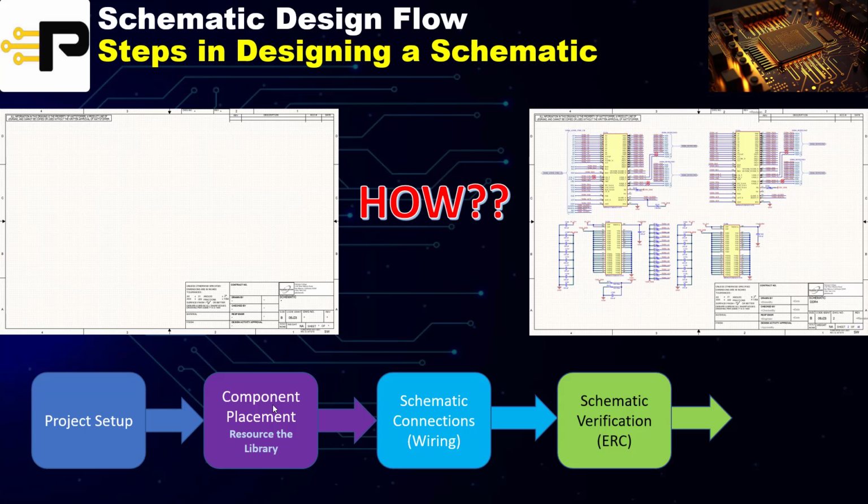Lastly, you want to have a schematic verification. This is done as a gatekeeping item, and I will be repeating this throughout other lectures in this series: schematic verification is a gatekeeping item, which means you will not want to proceed to the next step until you have a clean schematic to work with, and a verification that all the electrical rule checks have been done and you do not have any problems. The last step then is to push this into your PCB.